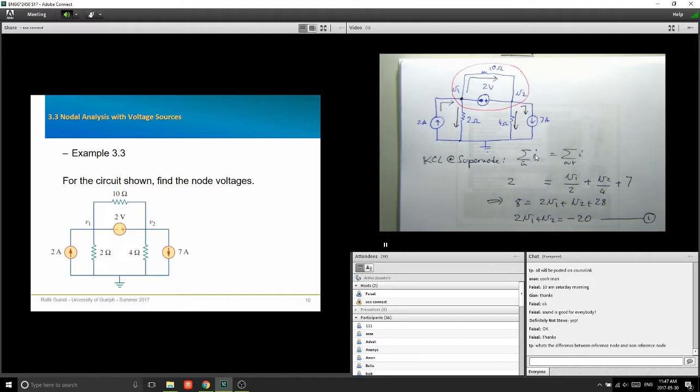You have a number of nodes, and we defined the concept of a node voltage, which is at what level of voltage or level of energy is any node compared to a reference. So to make the method work, we have to pick one reference. We're going to make that our reference node, and we're going to assign a voltage of 0 to that one. So this node, which is the bottom node here with this symbol down there, is assumed to have 0 volts. So you don't need to solve for that one. Okay.